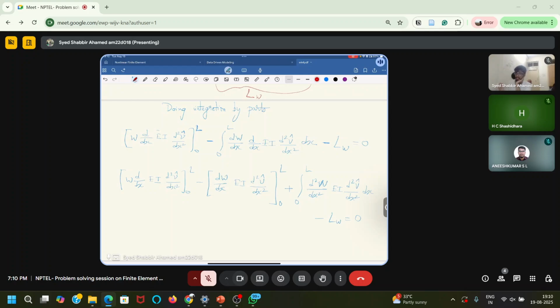So if we had taken a strong form directly without taking the integration by parts, we had to assume a solution which should satisfy this derivative condition. So you had to take a function such that it should be differentiable four times. But now you can choose v cap such that it will be differentiable two times. So the condition has been relaxed.